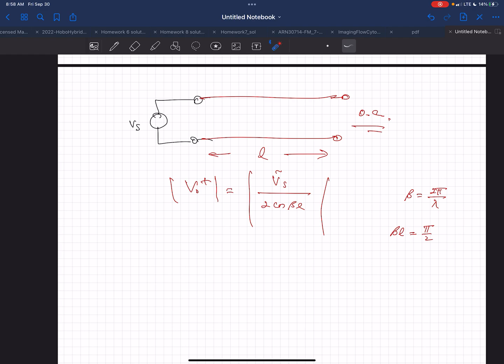Okay, they noticed, whoever it was, Ferranti or maybe the investor for this power distribution, that under certain circumstances, the voltage at the input of this power source was actually higher. I think it was a 200 kilometer, 120 mile power transmission line. The voltage at the far end was higher than what they were inputting. They noticed that.